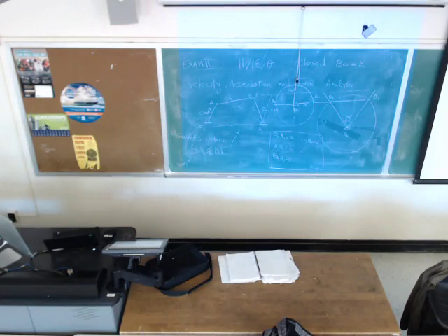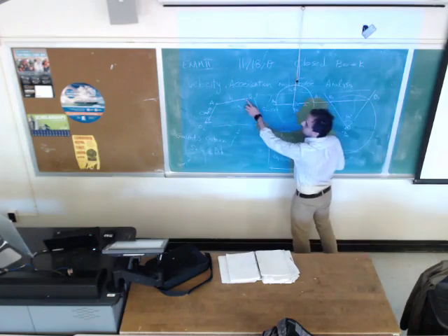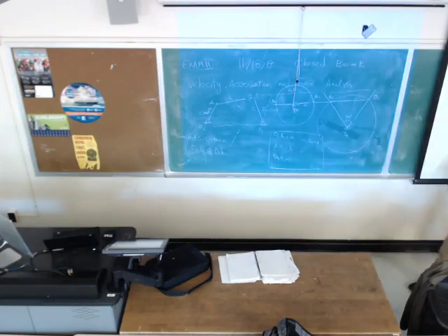So if you remember, for a crank rocker mechanism, you can find the minimum and maximum transmission angle. What if I add more restrictions on this design? I would like the maximum transmission angle not to exceed 135, and gamma min should be greater than 60 degrees.